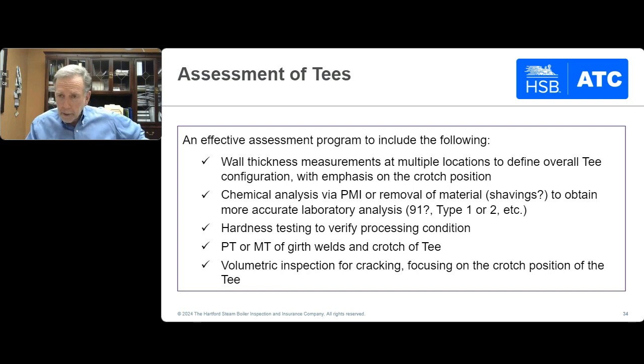The second thing I want to point out is that in this case, these units are not heavily cycled. So this again is not a situation related to rapid ramping up and down of the units multiple times over the course of the year. Keep that in mind, particularly in relation to what Jay just talked about in terms of the inherent weaknesses associated with some of these T's based on that lack of reinforcement. Now, nobody knows exactly what the total population of T's that may be at risk out there is, although it's generally conceded the number is fairly large.